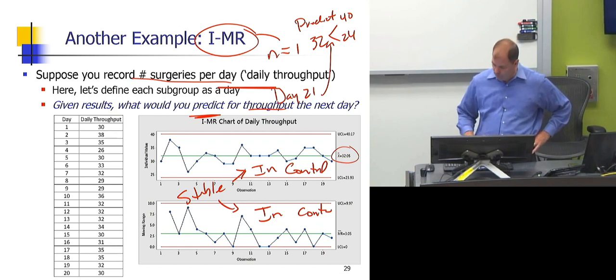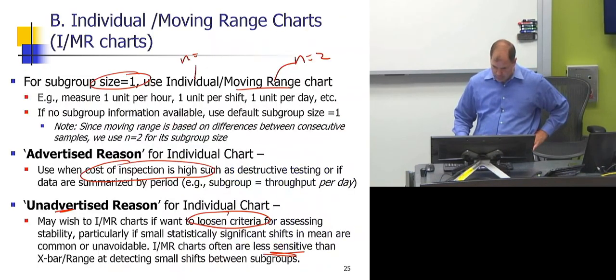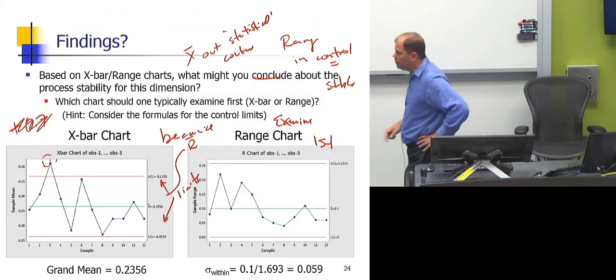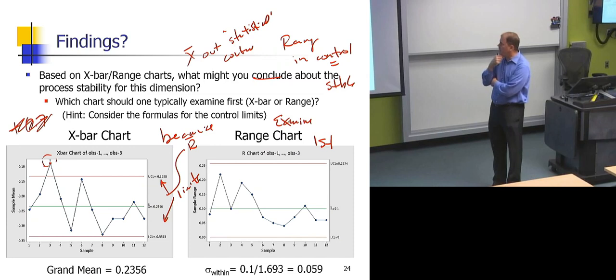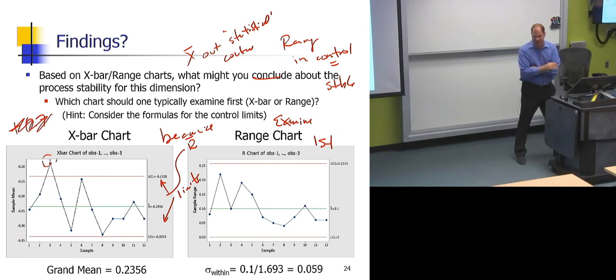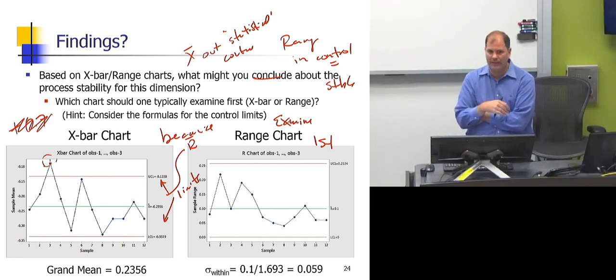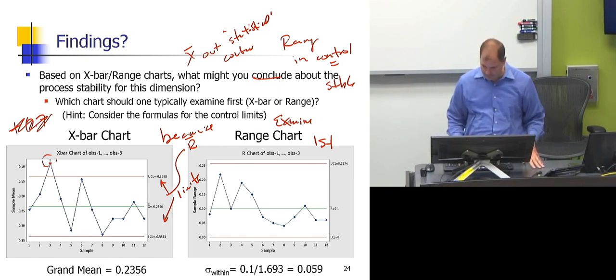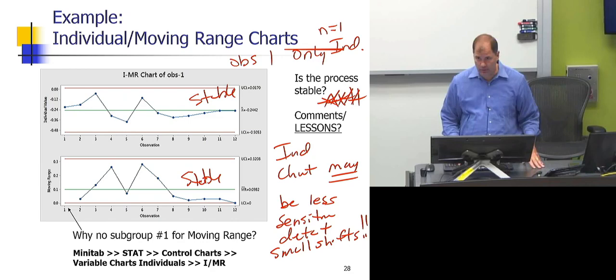If I was out of control, what would you predict as the next mean of subgroup 13? What would you predict as the next mean for subgroup 13? You would not predict. The process is not in control. We don't make predictions. That may be different if I was forced to, right? But the concept here is if I'm out of control, we don't make predictions. We make predictions based on an in-control process. I've demonstrated that I'm stable. How are we doing? We okay with that?